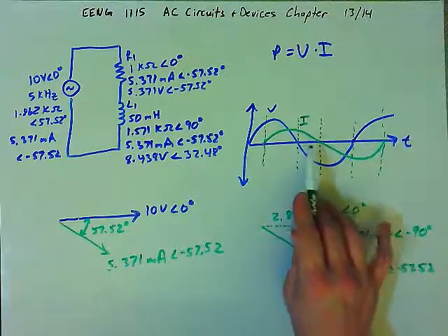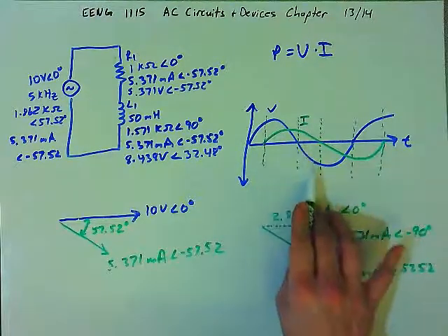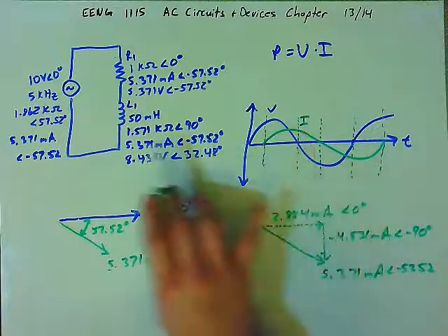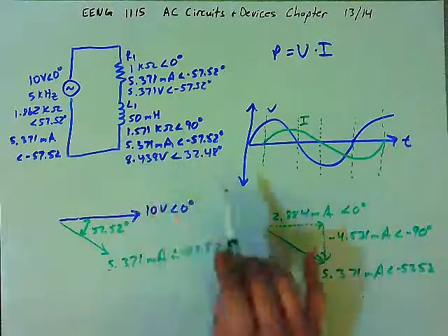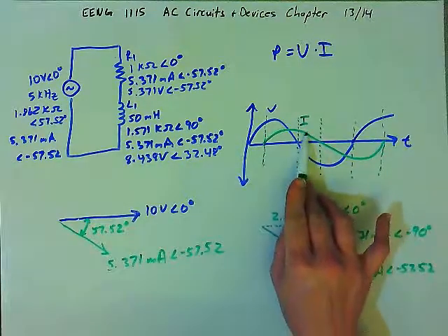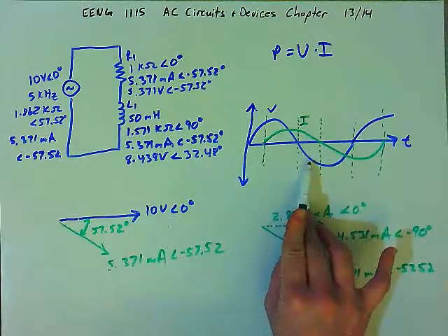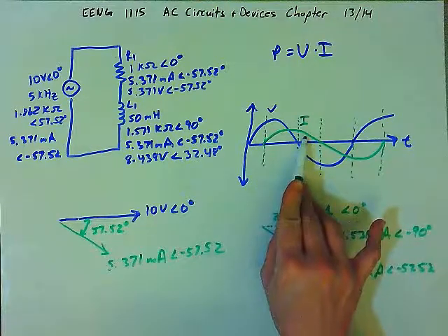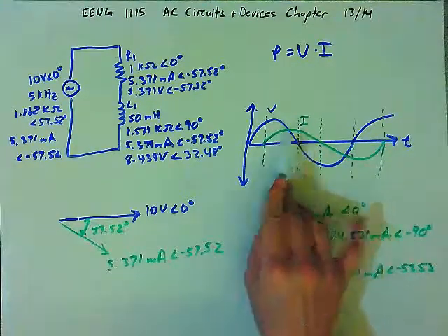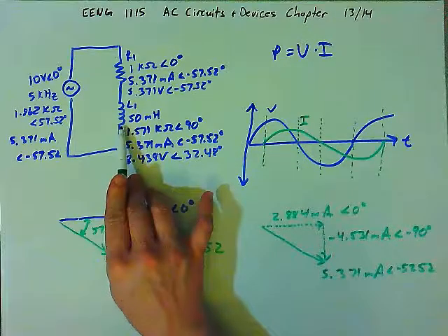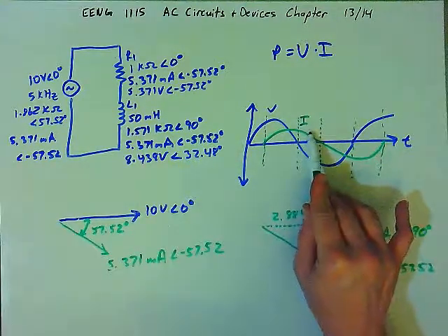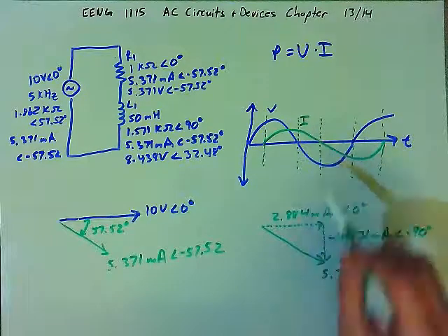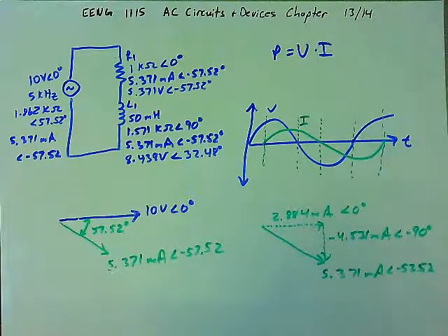And so what's happening here is the voltage is negative, but the current is still positive. That's because the magnetic field around the inductor is collapsing, and it's keeping the current flowing in the original direction even though the voltage has reverse polarity. And so here the current being supplied to the circuit is the energy being given up by the collapsing magnetic field. And so that was energy that was previously stored. So we consider that the imaginary component of the power.